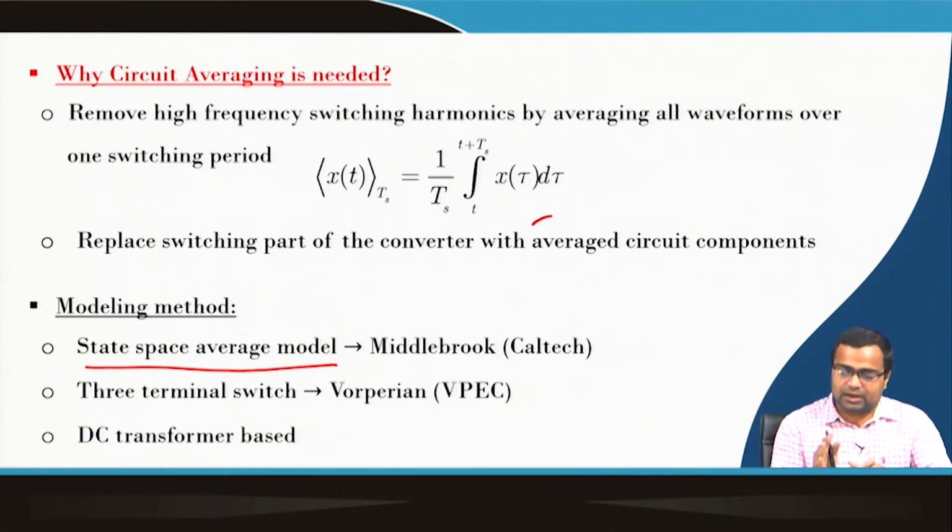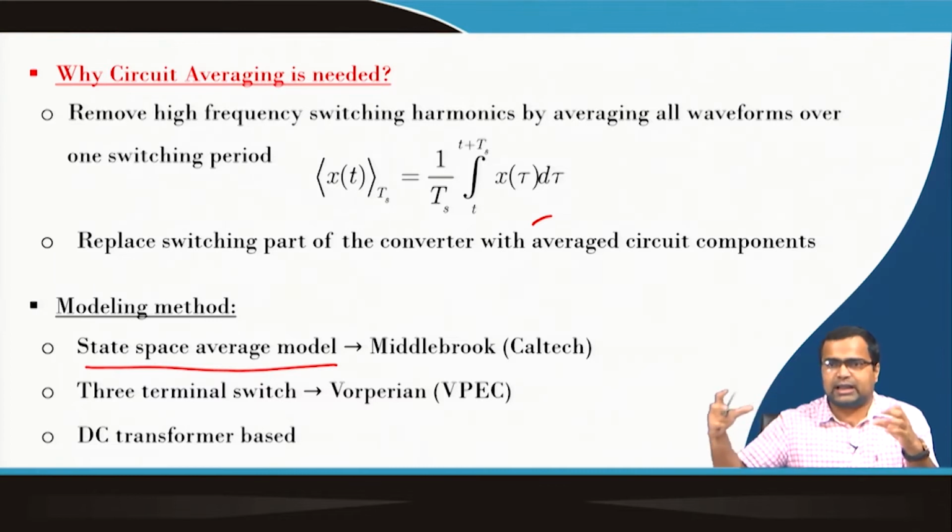In this method, the average switch model, there is a benefit, because if we incorporate some additional dynamic element, the switch model will remain the same, only the dynamic element will be added. The same approach applies, only the circuit has to be expanded with an additional element.